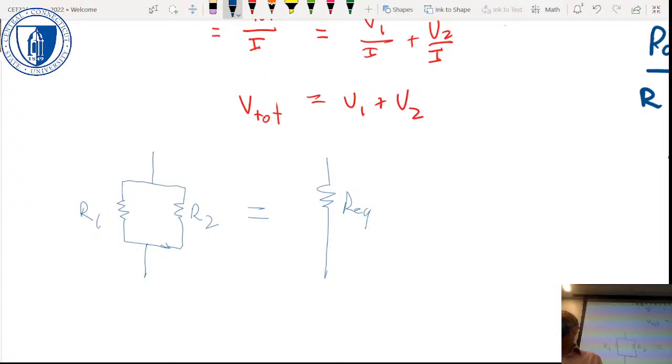Right, and the reason we could do that is because there's an area of constant voltage, and there's an area of constant voltage, and R4 and R5 are connected between the same two areas of constant voltage. This is also a node, but it's not the same node, so R2 is not in parallel with R4 and R5.